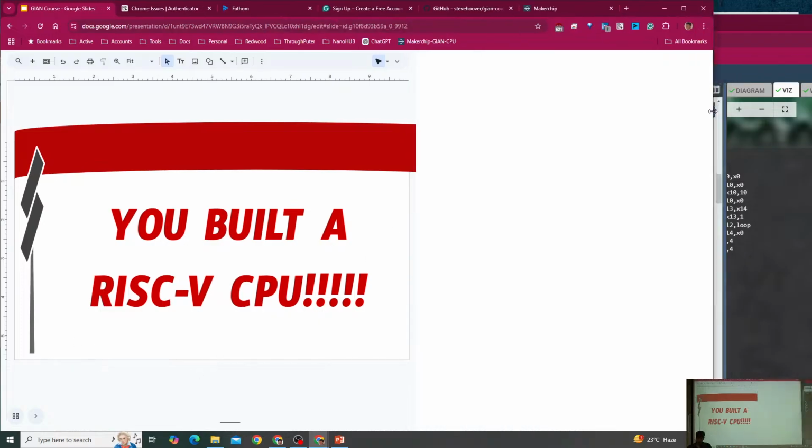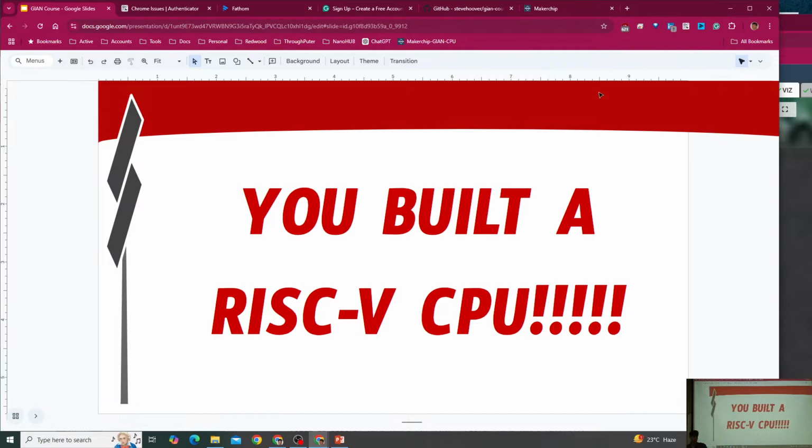In case folks have more bugs to resolve, I'd say we take another 15 minutes. If your cores seem to be working, you can use these 15 minutes to do additional testing. So add some jumps to your program, test the behavior, see if you can uncover some more bugs, and refine your core more. But other than debugging, good job.